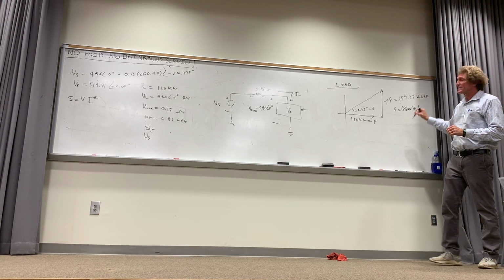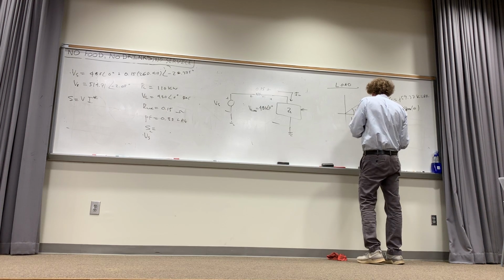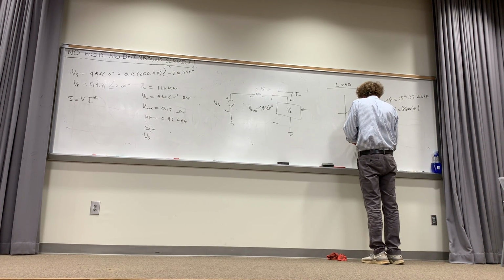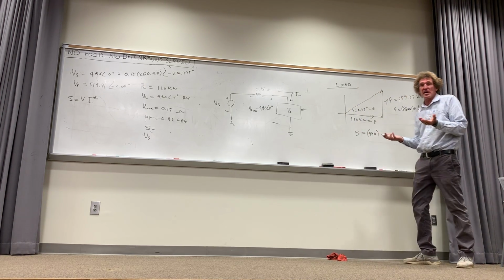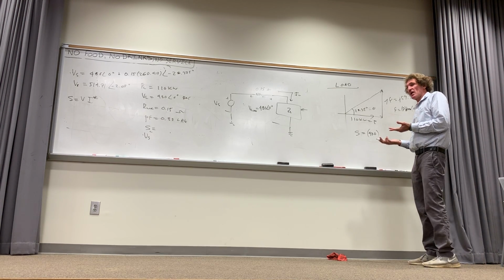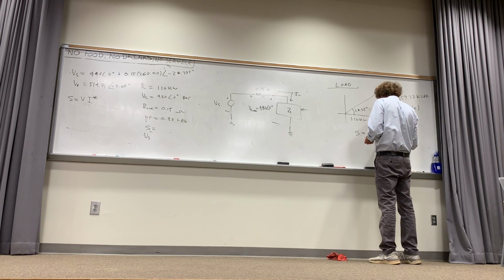Now, that means S right here can be given using just the actual VRMS. So that would be 480, right? It's just 480, plus J nothing. Do you agree? Thank you. Everybody? That's times I conjugate, correct? And I conjugate would be what?